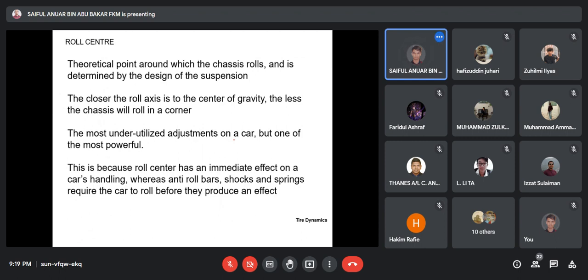Like I told you, in multi-body simulation, they not only tune the values for the spring and the shock absorber, they actually tune the suspension geometry, which comprises the hard points. Meaning where they're going to put the mounting for the suspension. For the strut, the upper point, where is it? Because that is going to affect the geometry of the suspension, and this one we call the suspension compliance.